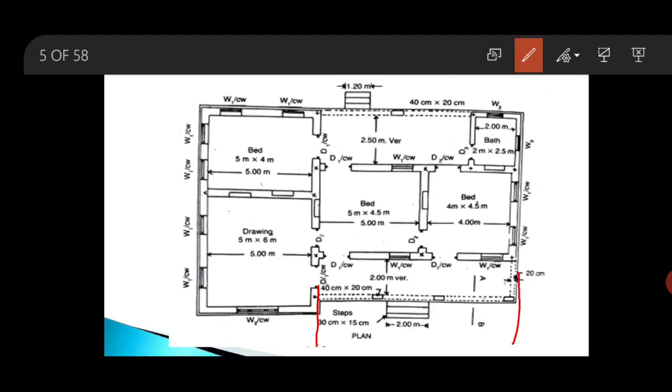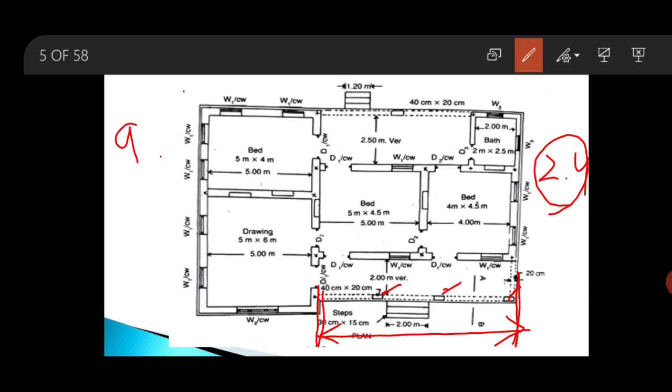So now we will deduct the size of the pillar from this total length for a height of 2.4 meter, because for this depth there is no brickwork excluding the pillars. So from the total length we will deduct the size of the pillar. This particular out to out dimension will be 9.6 meter. How much will this out to out dimension be?